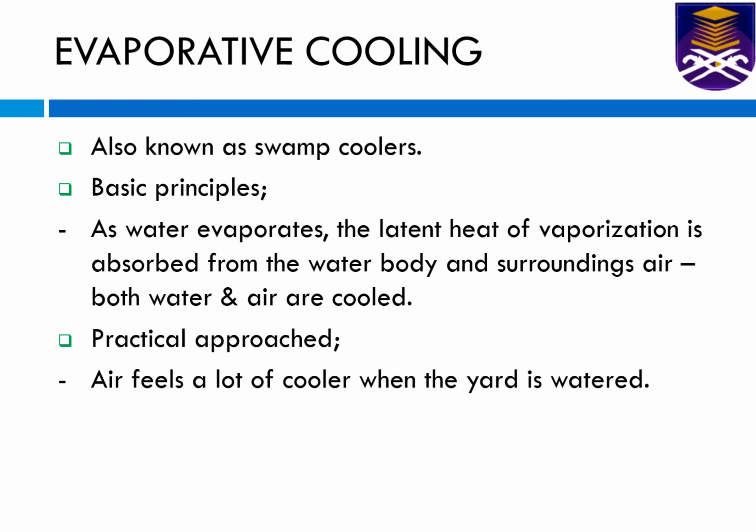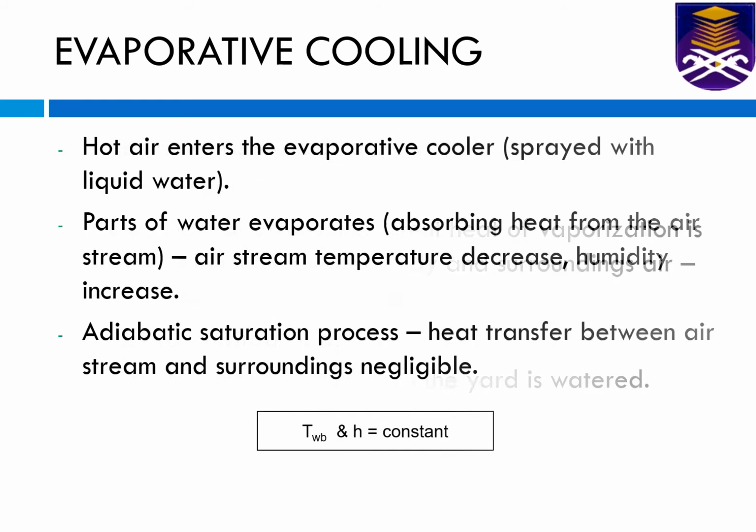So the next one is evaporative cooling. This is evaporative cooling, as in swamp coolers, due to the nearby condition where it will be cooled with the amount of water evaporation. So it will feel much cooler. Hot air enters the evaporative cooler and is sprayed with liquid water. Part of the liquid absorbs the heat from the airstream, and then the airstream temperature will be decreased and humidity will be increased.